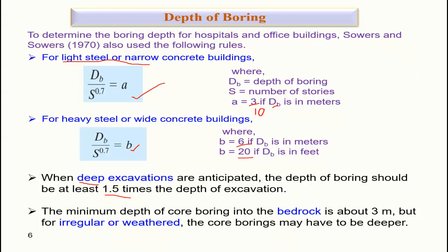In case of bedrock, which I said I will discuss later, if you encounter bedrock, usually you go 3 meter, right? Because the bedrock is the ultimate state of soil, it has very high bearing capacity. So usually 3 meter of testing is good enough.